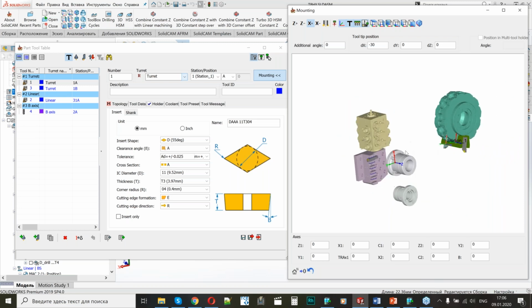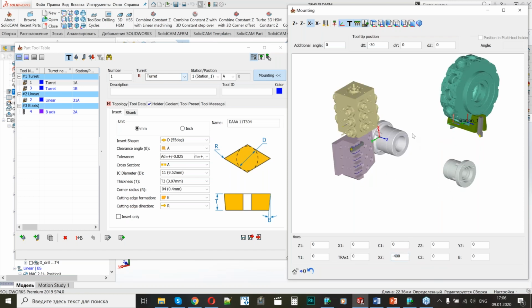I will remind you a little bit about the axis structure of this machine. The subspindle of this machine has 2 axes. It has X-axis, so it can move towards the main spindle, and to provide the operations on the turret and the back spindle, I should move the back spindle right opposite the main spindle.